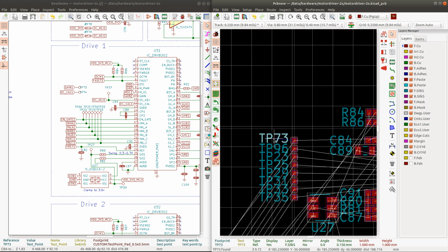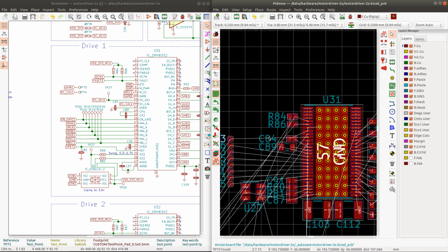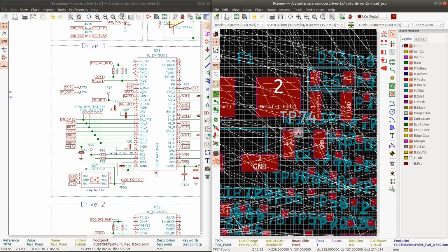So you basically amplify the voltage across the current sense resistor, and what you get on the output is either, I think it's 20, maybe it was 10. Anyway, there are two gains to choose from on this chip. And the DC cal is for measuring the offset.